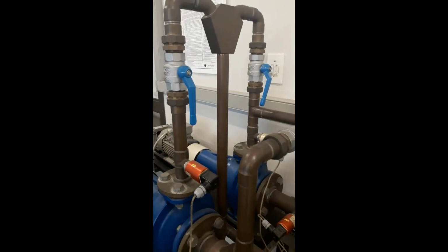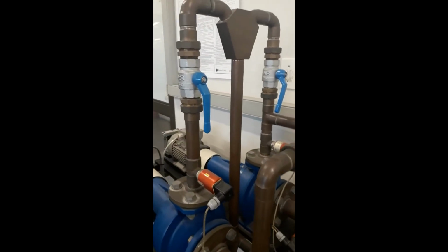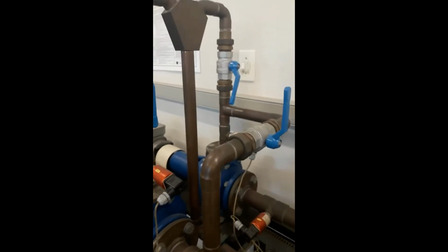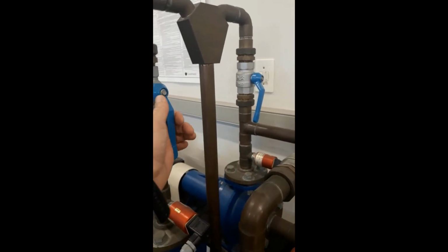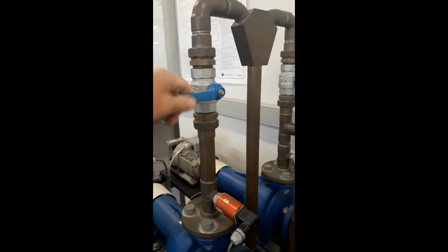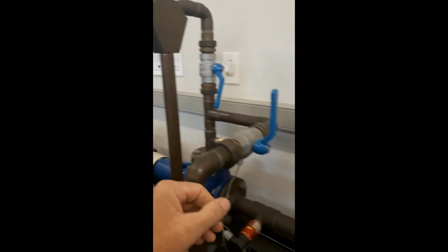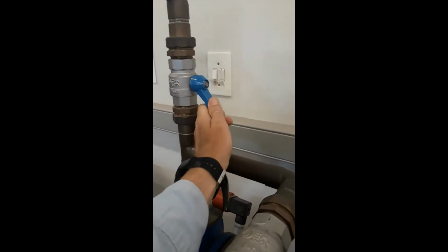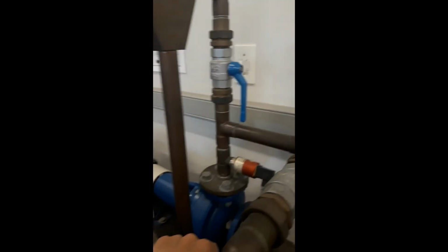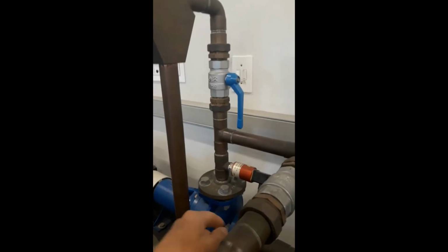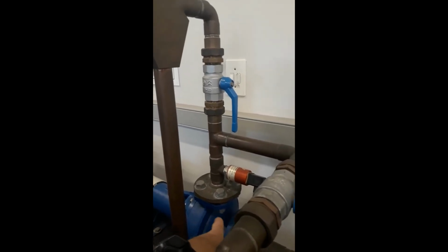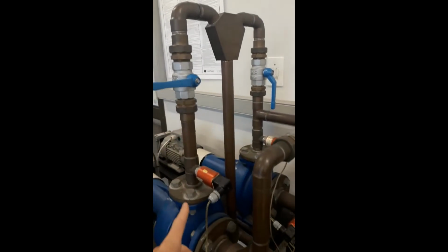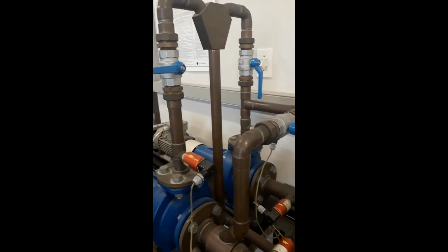These blue valves over here, we're going to make use of them to connect the pumps in series and parallel. If we want only one pump to run, we make sure we isolate pump number 2 and also the interconnecting line, and then we have to make sure that pump number 1 is open. Then when I switch pump 1 on, the water will be sucked through pump 1 and delivered, and it can't interfere or go into pump number 2.